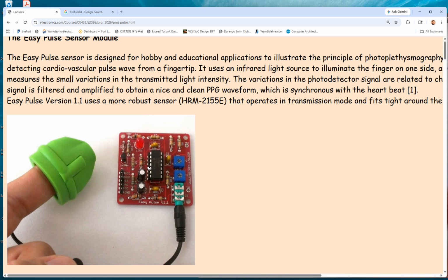You are outputting 0 to 1 volts from the amplifier, and you want your FPGA to treat that voltage range as 0 to 1 as well, not 5 to 6. Does that make sense? The only way to do that is to have a common base. Whenever you have a common base, the amplifier lifts it to 1 volt, and the FPGA will see it from 0 to 1 as well instead of 5 to 6, because they have the common base. That's why you need a common ground.